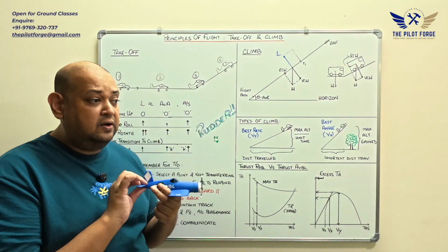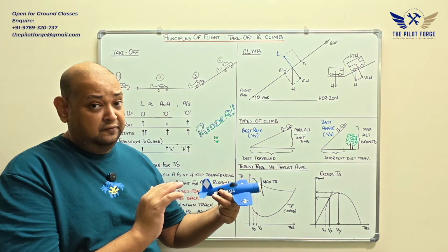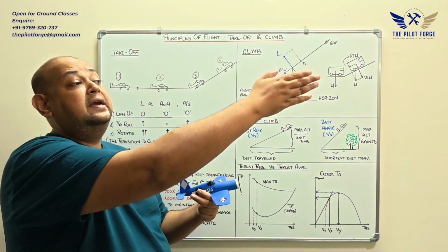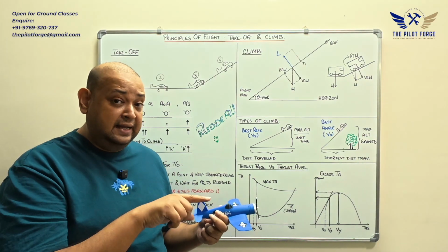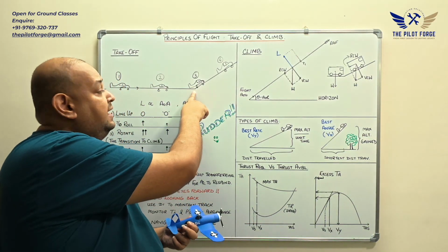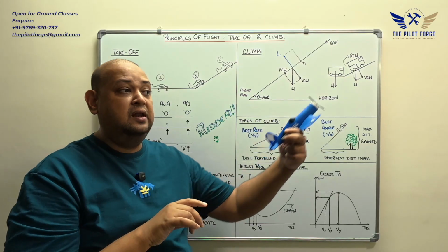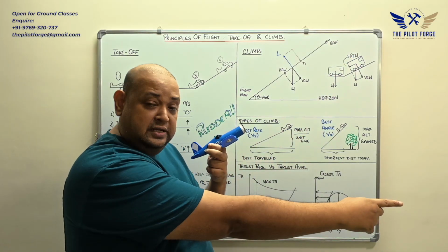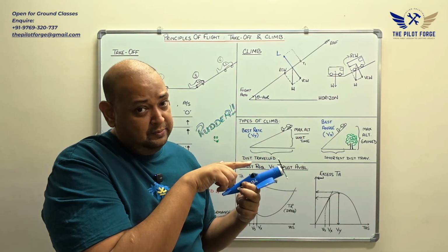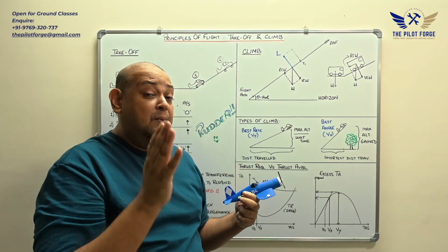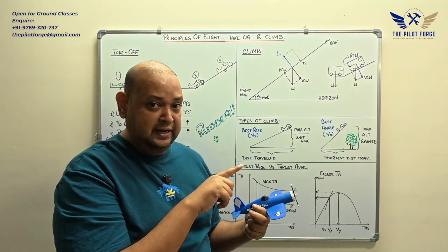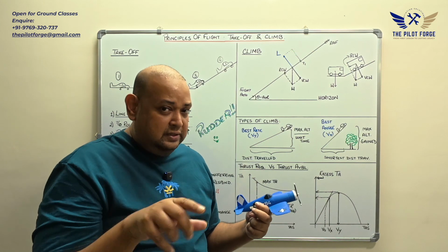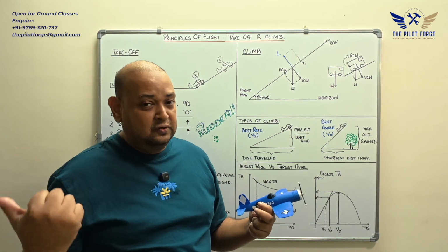So when you see your aircraft approaching the reference point from far away, you need to keep transferring it further and further away so you have a reference point that allows you to maintain that runway centerline, especially as you rotate and start climbing out, where that reference point is still on the ground and you might not be able to see it. In that case, you might have to transfer that reference point to the topmost point of your direction indicator.